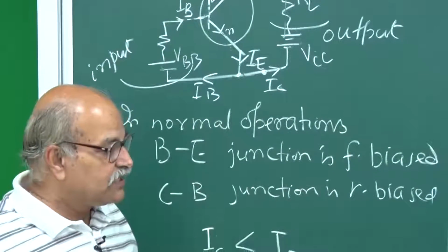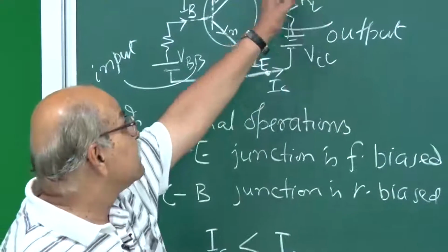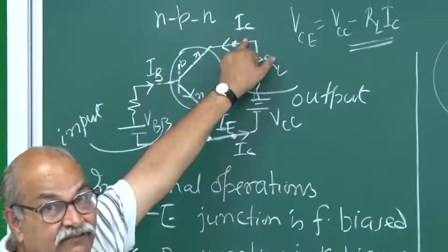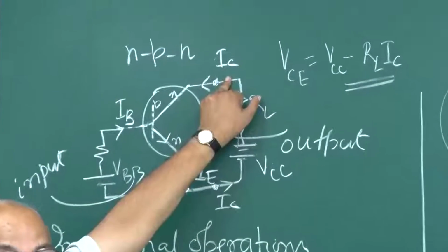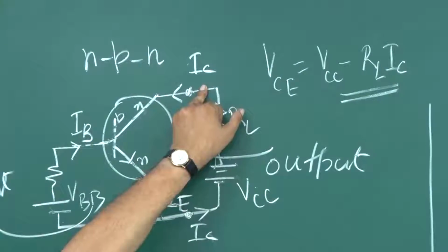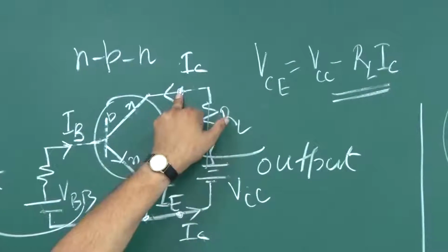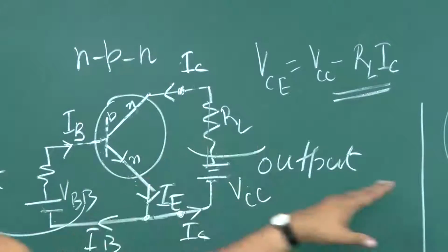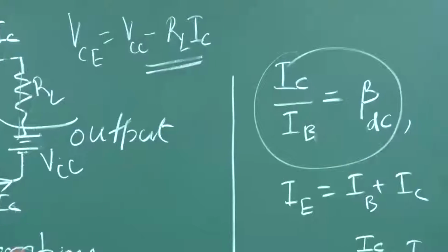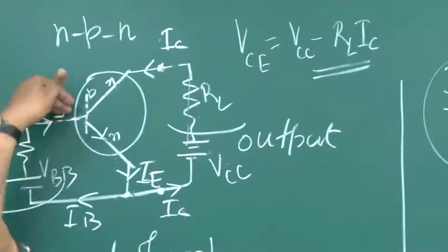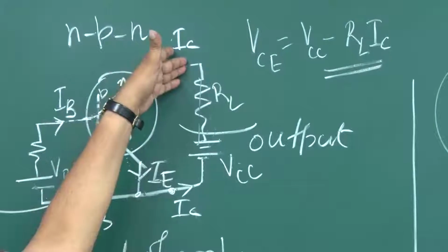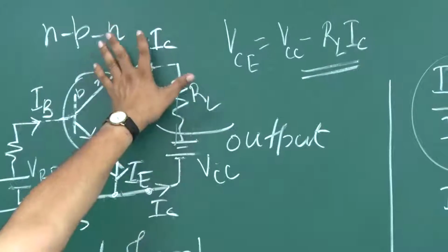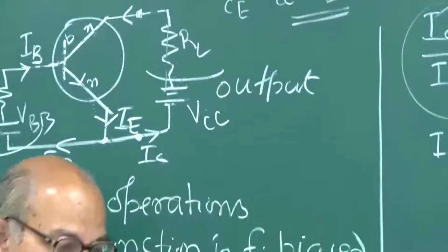And then we have this saturation region, where the current is there, the transistor is active, but the capability of drawing more electrons here is saturated. In that case, this IC will be smaller than beta times IB, and if you increase IB, this collector is not ready to respond. So you do have some kind of a constant current after that. These are the regions.